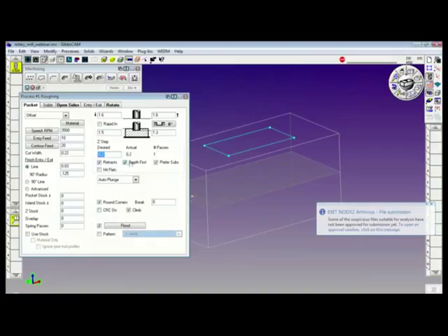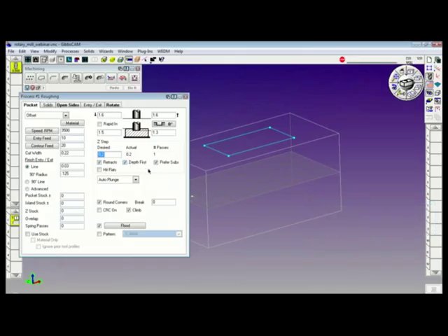I'll use retracts, depth first, prefer subs, auto plunge, and round corners is on. It should always be on when machining. Even if you're not breaking the corners, just use a 0 corner break. You'll get a better tool path using round corners. You'll roll around a corner instead of bypassing it and changing direction with round corners on.